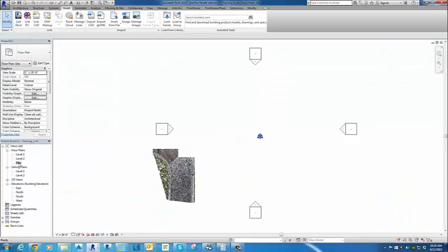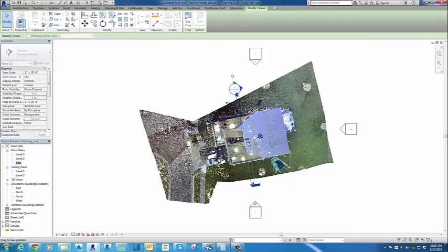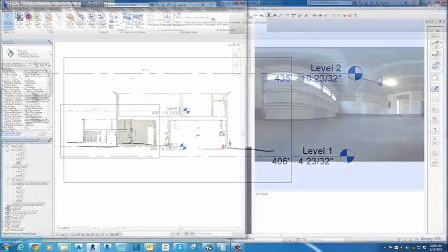So now for our next step, I'm just going to set up some levels for us to design so that when we start doing our walls, our levels are set at the correct height, and our walls will then also restrict to those level heights.